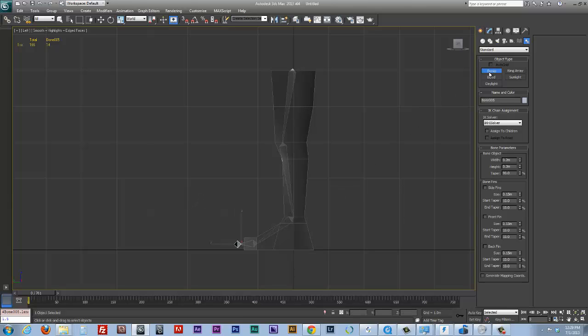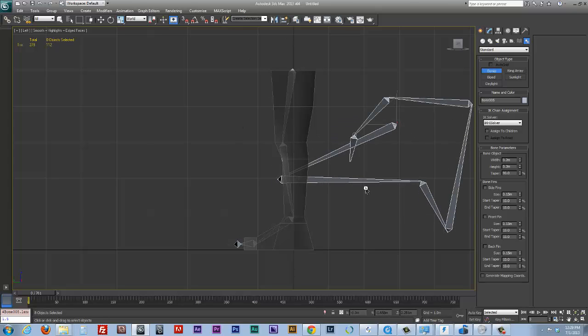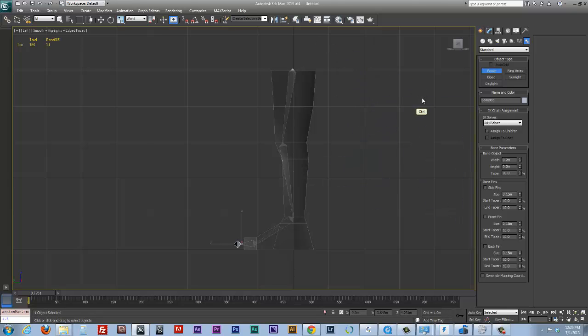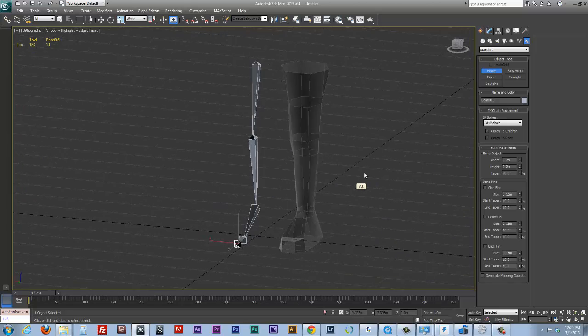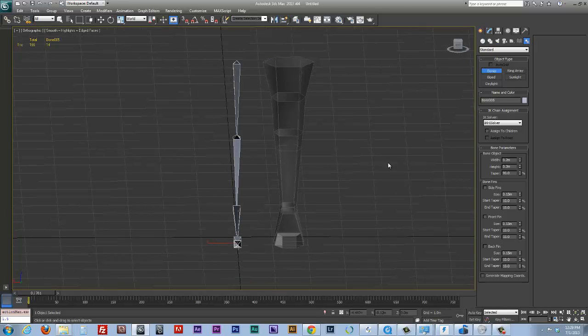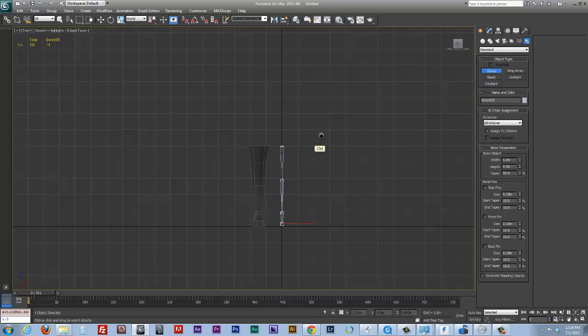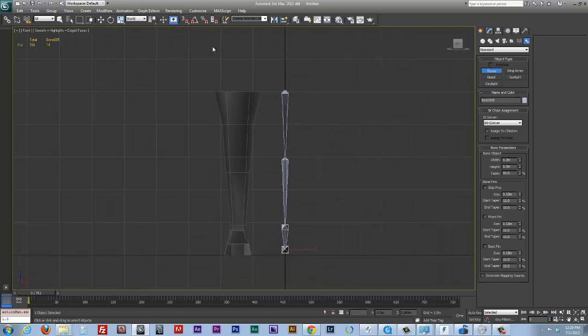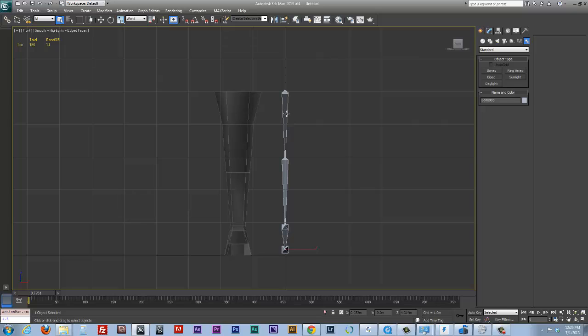And you're still in bone create mode, so any place you click in the window at this point is going to keep creating bones, so you don't want to do that. So let's undo all of that and turn off bone create, and we have our leg. But if you look to the front viewport, you will notice that it's offset from our actual leg mesh. So what we want to do is select the top of the hierarchy, which is the first bone we created. I'm going to hit W for move, and we'll position the entire chain into the leg mesh, like so.